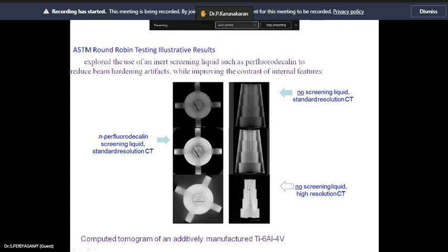So based on the material used, suppose it is a ductile material, it may lead to different behavior compared to a brittle material. The alloys that are prone to hot cracking and solidification cracking have proven difficult to process. So already we have some materials with proven cracking in hard conditions, and these may be avoided in a particular processing like SLM.